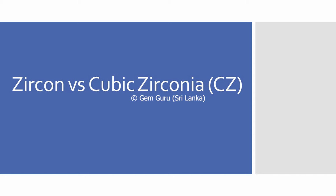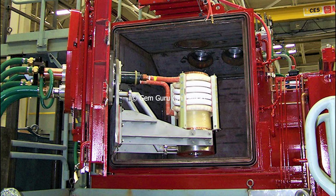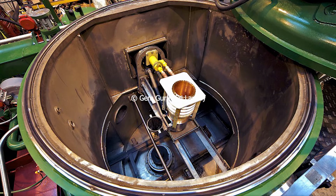So the commercial production of cubic zirconia began around 1976. In the synthesis process of cubic zirconia, the skull melting process is adopted because the process can achieve over 3,000 degrees Celsius inside the crucible. The melting point of baddeleyite is about 2700 Celsius. So because of that, to produce synthetic cubic zirconia, the skull melting process is used.